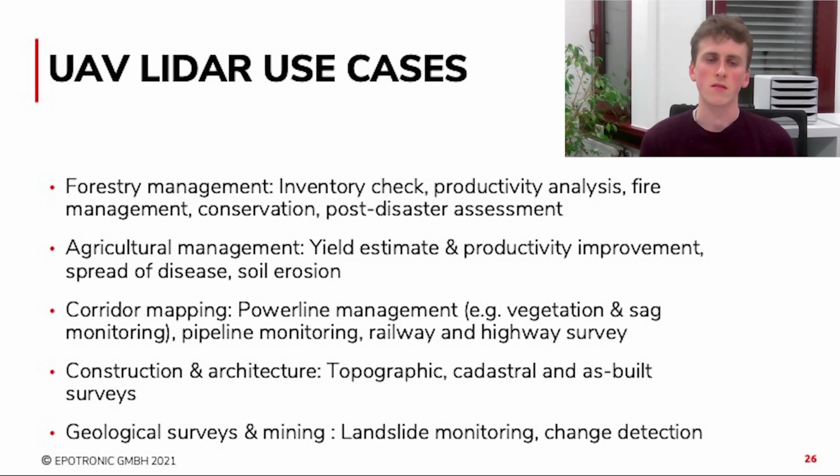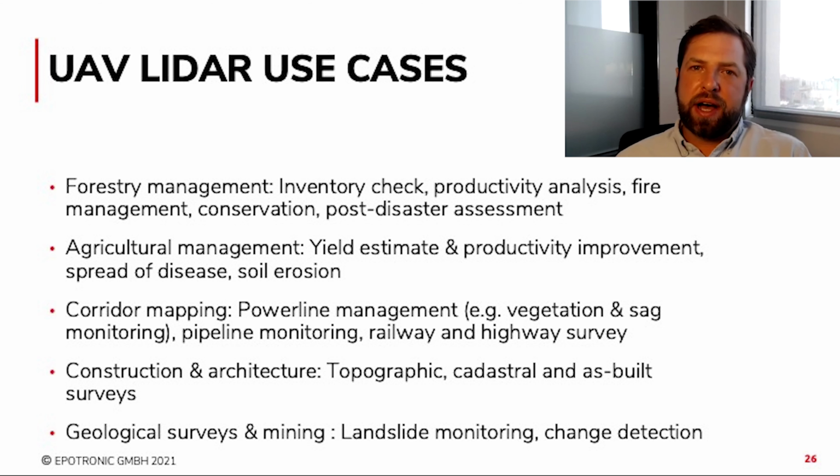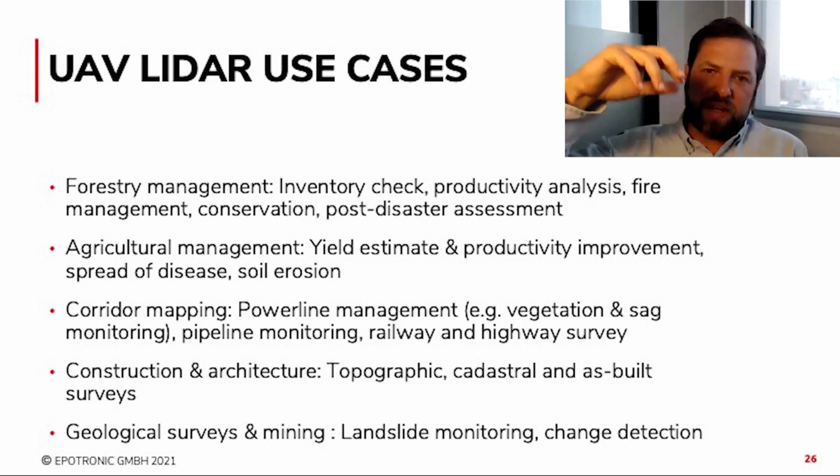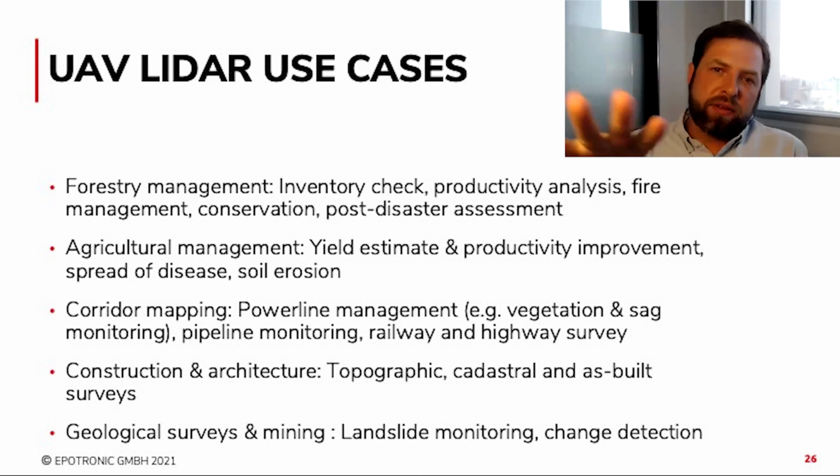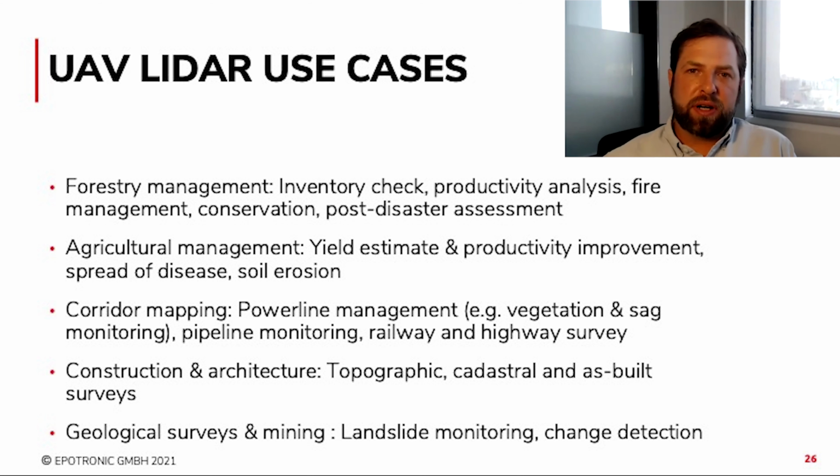Yeah, water, like everywhere in the world, is an extremely important natural resource in California. So one of the issues in forest management is making sure that your road networks are not committing too much sediment to the hydrological system. So there's a lot of benefits to being able to use that LiDAR, which can penetrate the forest canopy and the vegetation to model basically the terrain and then do erosion control analysis and monitoring.